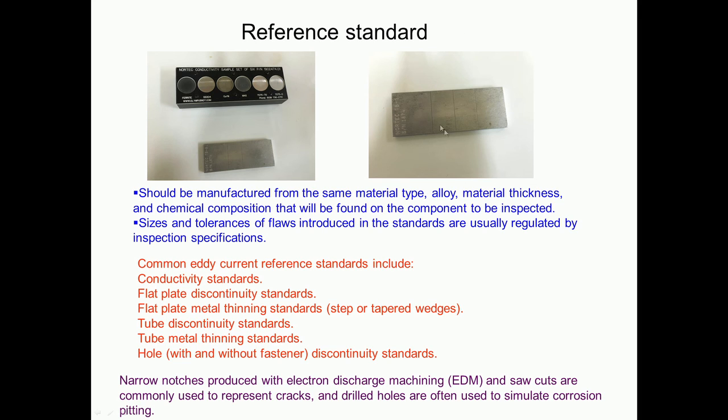So, this one you have seen in the video, which have this precisely cut lines which represents crack, which is here also. This is a conductivity reference standard, because you have seen conductivity is one of the important parameters which controls the depth of penetration of the eddy currents. So, in certain cases you need to calibrate the instrument with regard to the conductivity as well.